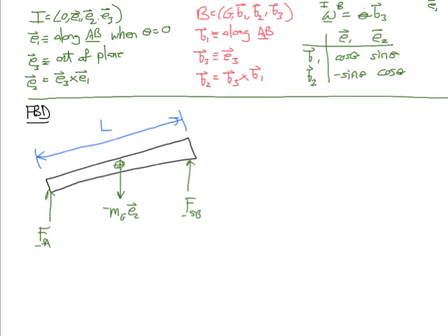And so now let's define our spring forces in the basis vectors that we have. So take the spring force at A. Our model for this is negative K, spring coefficient, of L minus L naught, where we have the length of the spring minus the resting length, and this is in the U sub S direction. And in this model, U sub S is defined as the direction from the attachment point off the rigid body to the attachment point of the spring on the rigid body. Let's define each of these components.